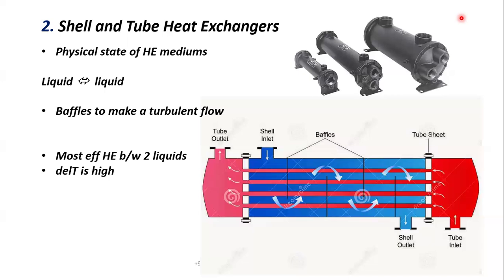I've seen the cleaning of this tube. Oh yeah, you can see now. I think the tubes are much greater, isn't it? Like the size. Yes, sir. They use some equipment with a brush inside to clean. That process is called chemical flushing. Rotary flushing, I think. Rotary flush, that's it. Because in tubes, we might need this rotary flushing. I'm just explaining the entire process is called chemical flushing, for the whole pipelines, including the shell and tubes. So that is meant to be a shutdown project or maybe a maintenance project, whatever.